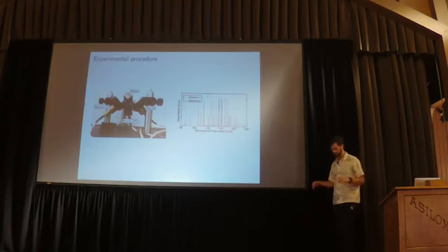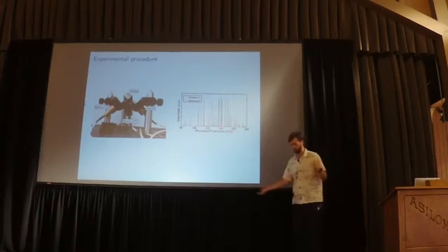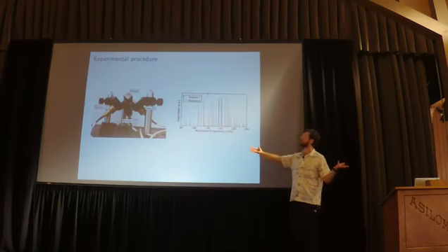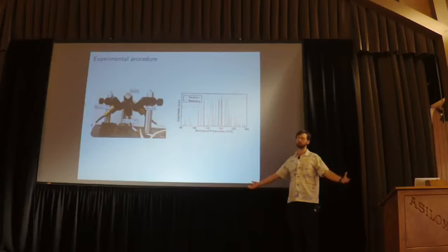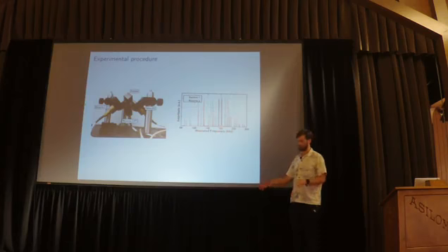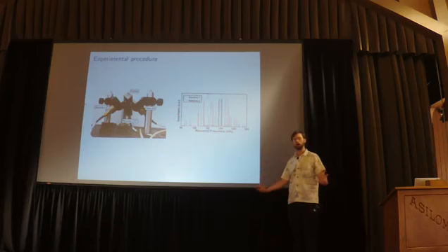We actually try to measure what are known as the resonance modes of a material, and when you're thinking about resonance modes, just think of gongs. If you have a big gong or a drum and you hit it with a hammer, it rings, and it will ring at a frequency that is a function of its geometry and a function of the elastic constants of the materials that went into it.